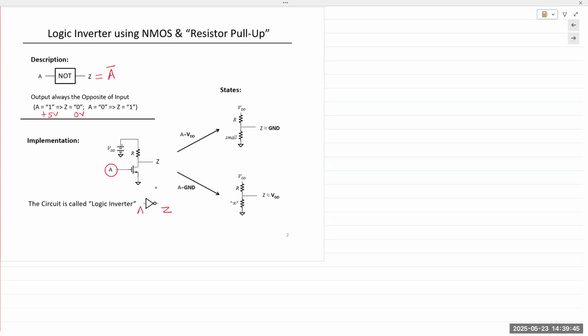Operation is rather straightforward. If gate voltage is 0, then the MOSFET is off, below threshold. If the MOSFET is off, then the output is directly connected to VDD. So you apply 0 at the input, and you get VDD at the output. Hence, inverted. Make sense, right?